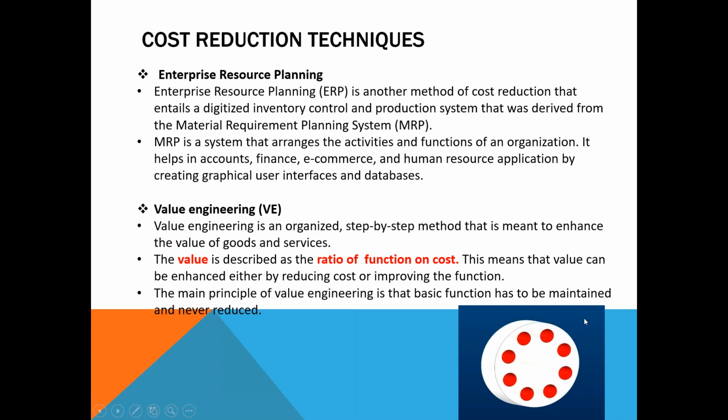Previously this forged part was made plain, and then an 8 mm hole was drilled, followed by deburring and chamfering. There were a lot of troubles. Now this forging with a hole is being produced in the forging itself. So what has happened? You have saved the cost of this 8 mm hole drilling, plus the cycle time or throughput time which was required to do this.